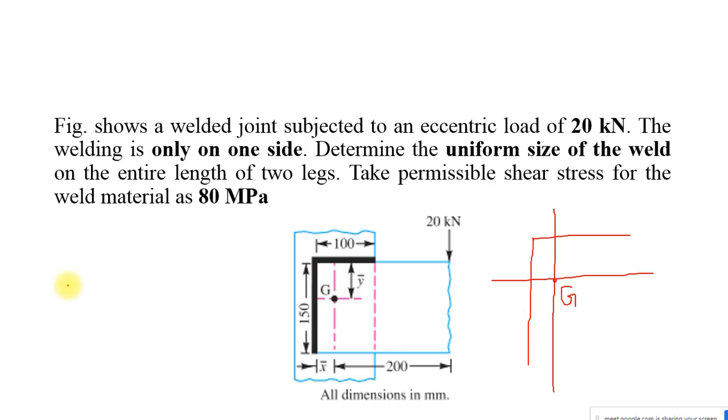So we have to find out what is nx and ny in order to find out what is happening here. Okay. So since we know that from this G we would be drawing like this, we may have this particular point as sigma 1, and at the inclination I have a sigma 2. This point is A and this point is B. So to find out this distance and to find out this distance, I need this particular nx and ny.